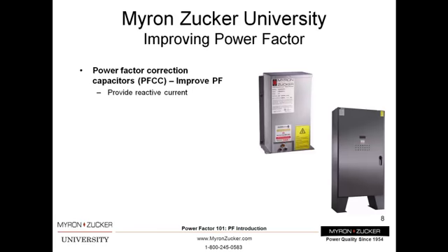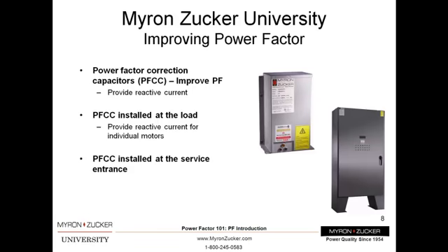Power factor correction capacitors can be installed at the load or at the service entrance. At load installations provide reactive current for individual loads, and service entrance installations provide reactive current for the entire facility. Service entrance power factor correction capacitors can either be fixed or automatic. Fixed systems provide a constant amount of correction for facilities operating with constant loads. Automatic systems adjust the amount of correction for facilities where loads are variable.